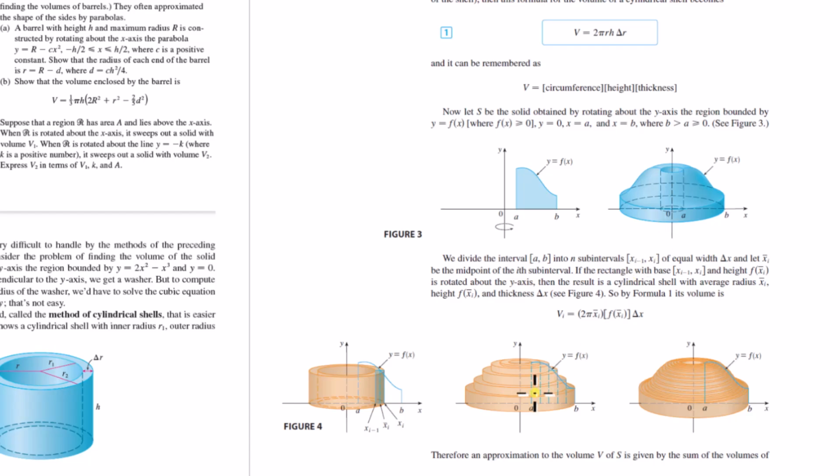But an important step when you're setting up an integral is to break it up into as many pieces as is reasonable, where you can still see and count the pieces. They put about 30 pieces. When you do this, you should clearly see that it is converging towards your desired shape. I want to find an example. I've seen examples where you might think it'll always converge. Well, no. You might set up an element and think it's going to work for this integration, and then when you apply 30 of those elements, it's clearly not converging.